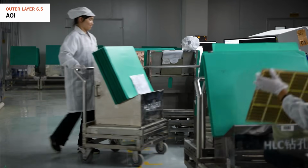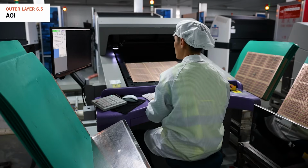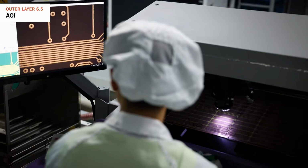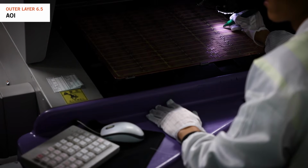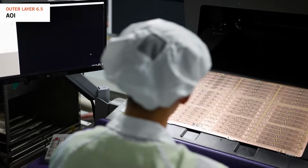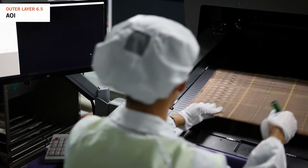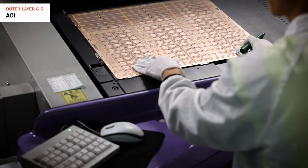The second stage is the verification stage, where operators check if the concerns identified during scanning are acceptable or not. They inspect the circuitry for issues like shorts, opens, missing copper or other damage to the copper pattern, ensuring that the circuitry, including conductor width and spacing, meet both customer requirements and IPC tolerances.